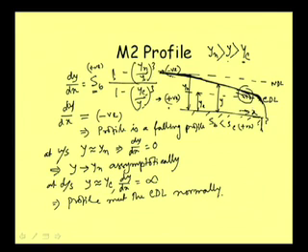So when we compute the flow profile at this point, of course, this zone is very narrow, very small, because the change in slope is infinite, meaning it is changing at a very fast rate. So in a small portion at the downstream end of the M2 profile, the condition of hydrostatic pressure will not prevail because of the curvature, and we may end up making some error at the point. Of course, this zone is so small that for practical purposes we can neglect that. Well,